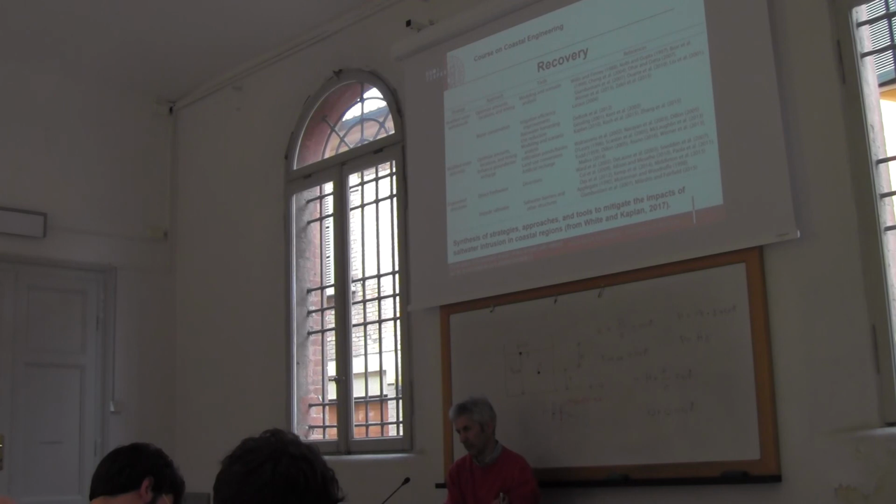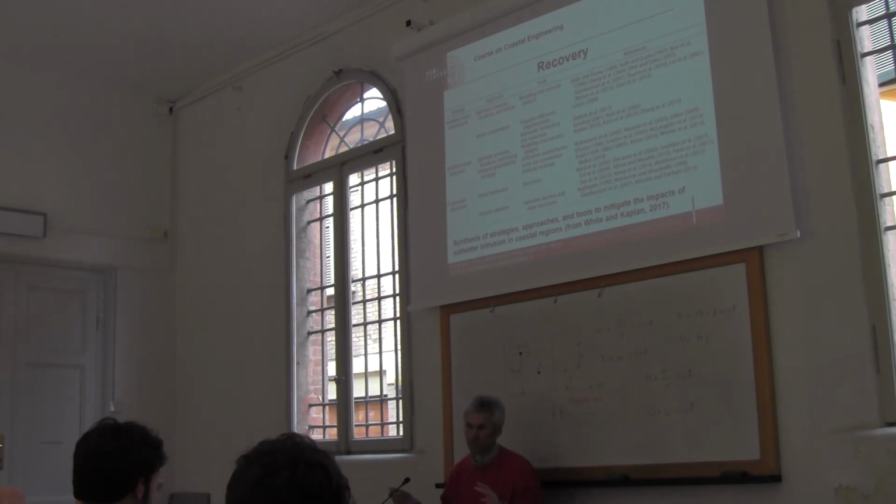So, in order to go back, what we can do is to modify our water withdrawal and water deliveries. So we have to reduce pumping from the well. We may also act by injecting fresh water into the well. It is an opportunity.